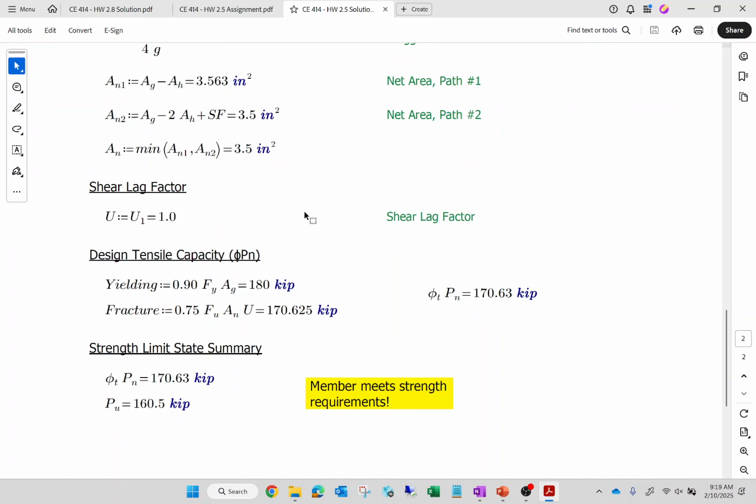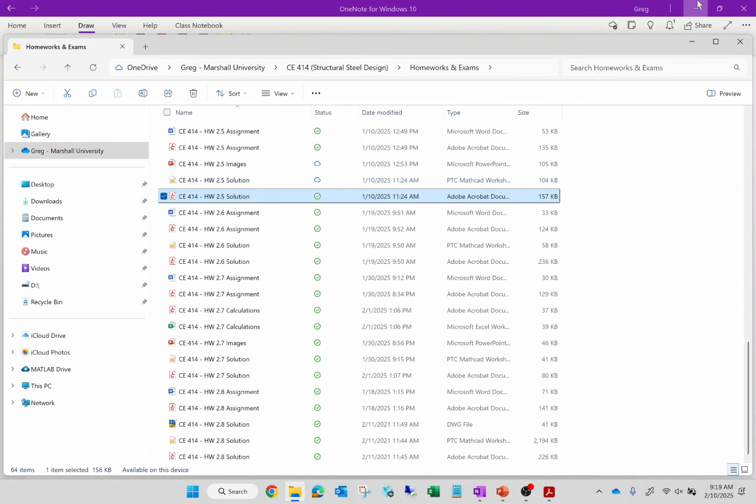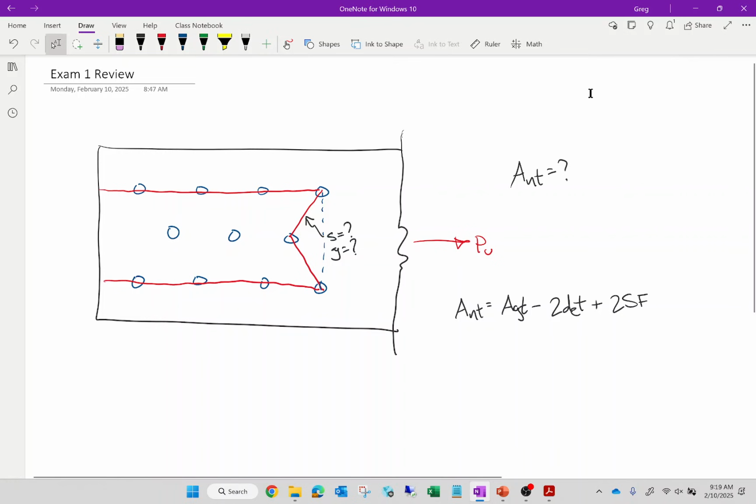We found 2 sets of LRFD equations in the slides. You did? Yeah, me and Mike have it pulled up. For one of them, it says equation 2 was 1.2D, 1.6L plus 0.5 times LR or S or R. That's an old one. The one that has 0.3 on the snow, that's the correct one.